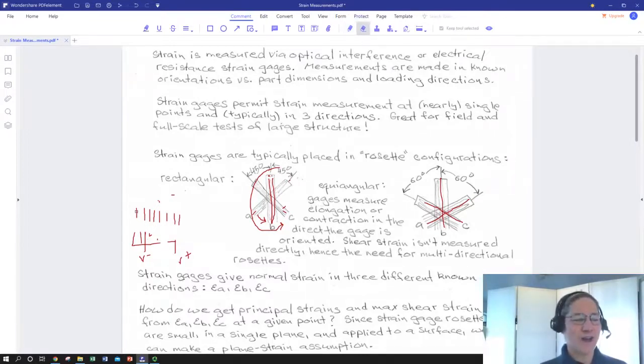These gauges, we're not measuring shear with them. We can only measure normal strain. So the strain values from our resistance changes in our gauges represent normal strain only. So we're going to get basically only the horizontal component of the Mohr circle coming from each one.